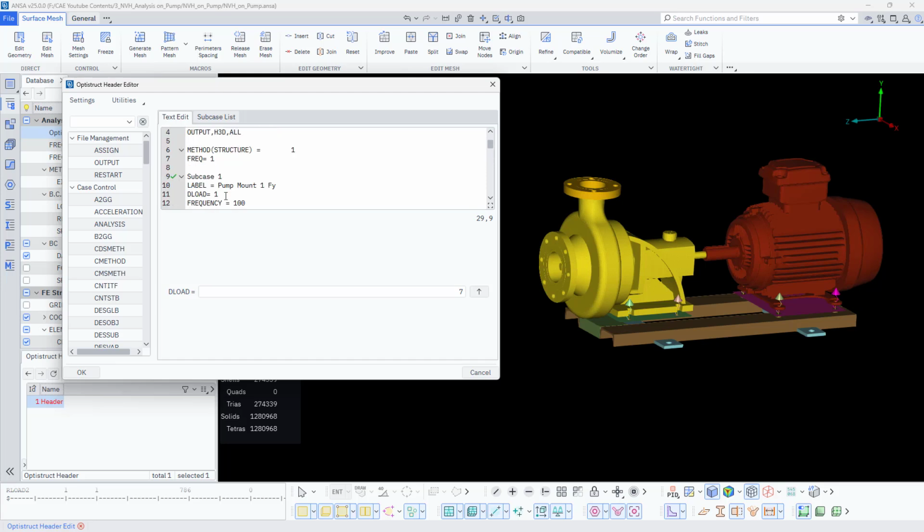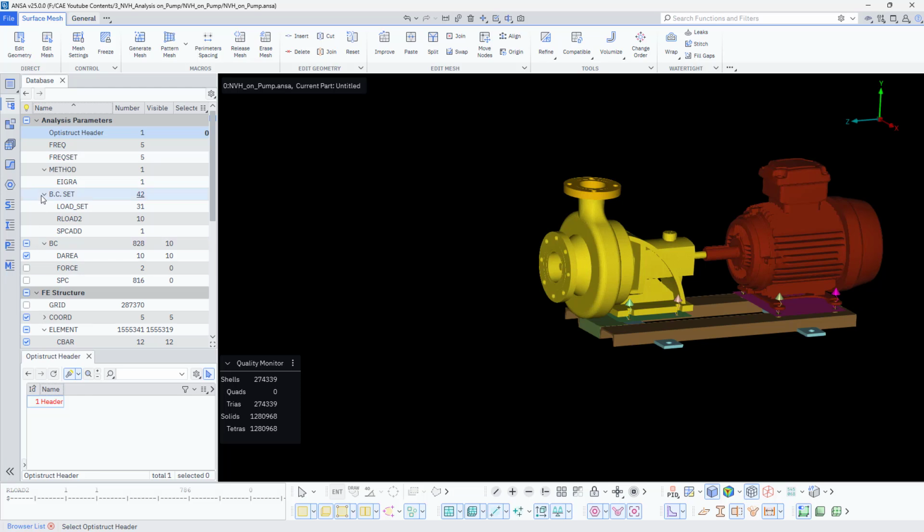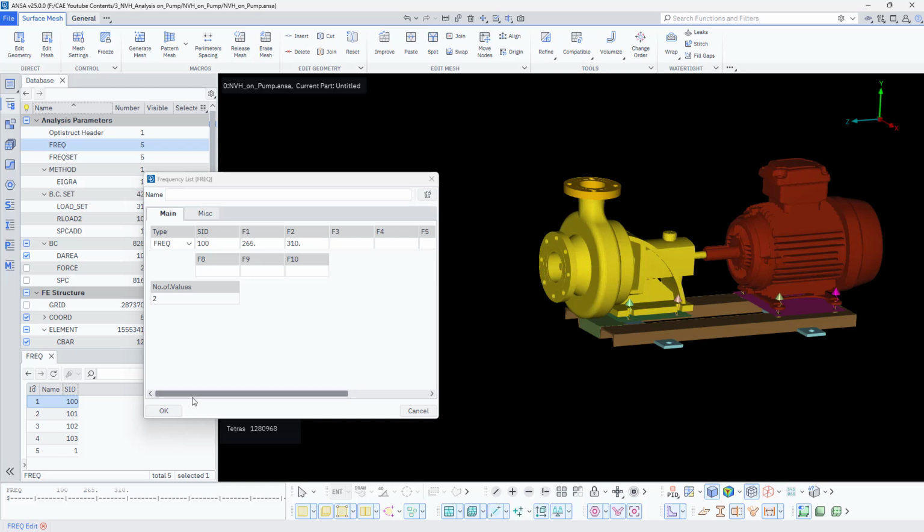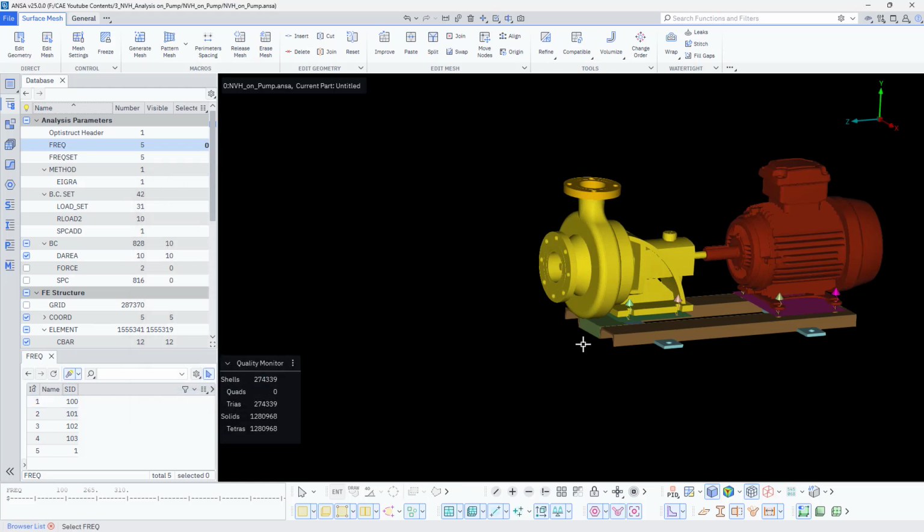I think this is all you can do for the ODS run. Here, yes, you need to define the cards, so 102, 103. You can even call a single one also, because in all the FREQ cards we have the same frequency, so we would have called only one, so no issues. So for information, you can have multiple FREQ cards, so that you understood, right? Well, so just for information, we just checked these FREQ cards, it's fine.